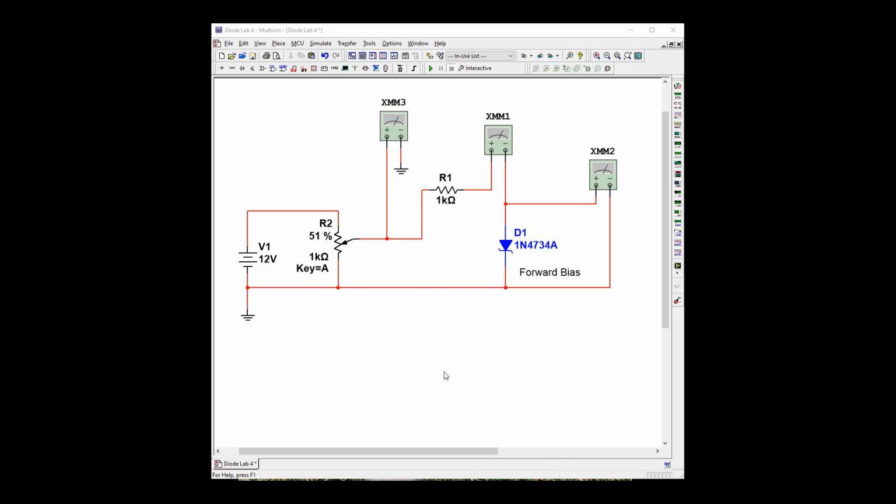Here we're back at Multisim for our part 2 circuit. I built this using a potentiometer, and we have 12 volts going in. This is a voltage divider, and we can provide a pretty precise voltage. Since we need to move the voltage and figure out what the current is, this is the best way to do that.